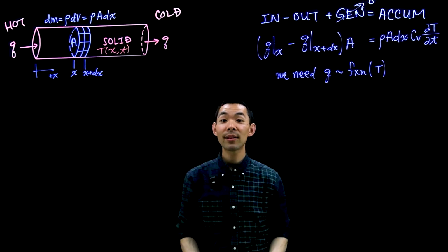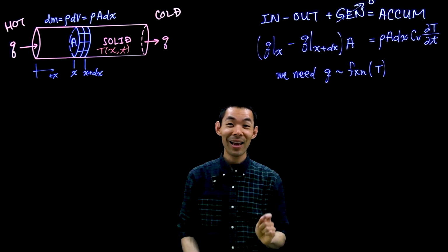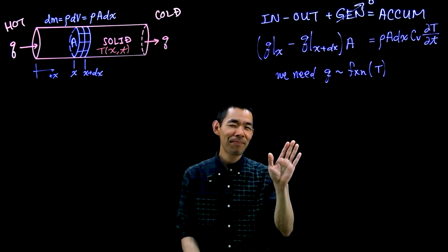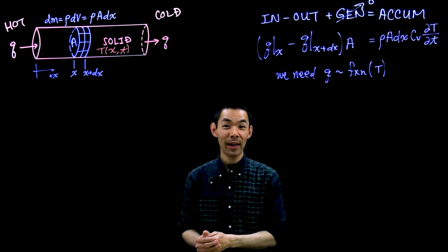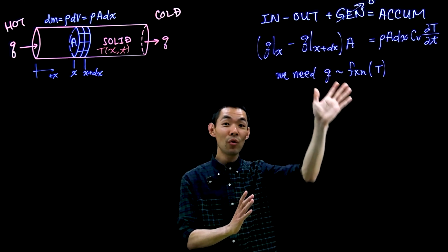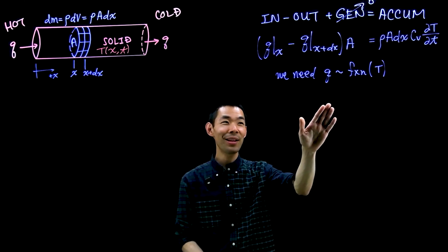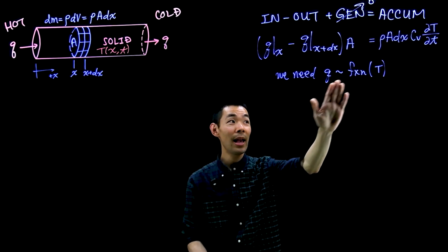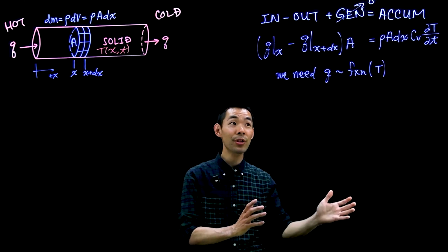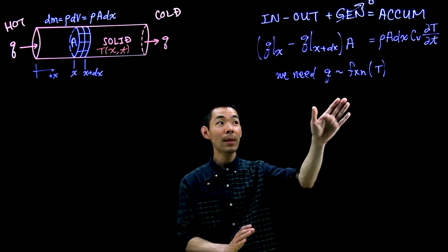This is called a constitutive relationship, and it actually is an extremely current and active area of scientific and engineering research. Not so much in heat transfer, but more so in fluid mechanics. In fluid mechanics, there is a similar relationship that we need to obtain when you do a shell balance over a momentum balance. And what you get eventually at this stage is a relationship between the stress tensor and the velocity, or gradients of that velocity. And once you have a relationship between those two quantities, you close the equation. So this is sometimes called a closure.